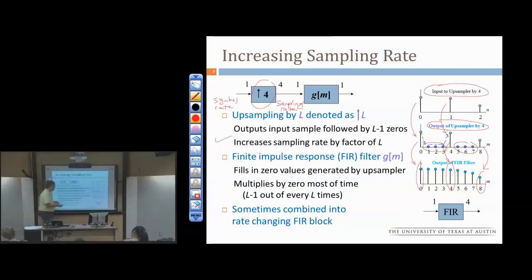So in order for the original values to stay unchanged, I need to make sure that as I do the flip and slide across this signal, when I'm here, the filter coefficient over here better be 0. I don't want any contribution of this one, and these are already 0.